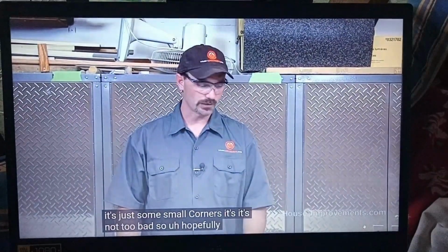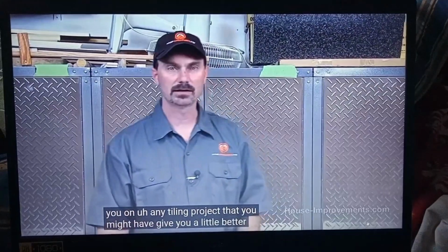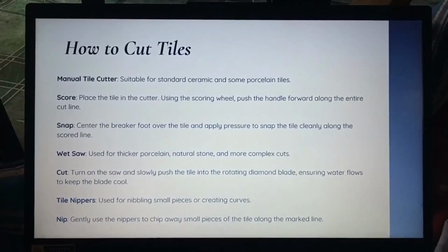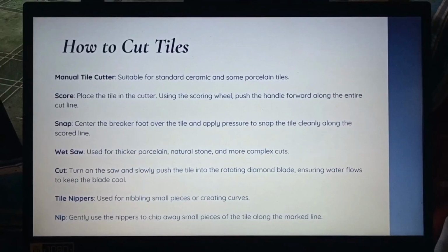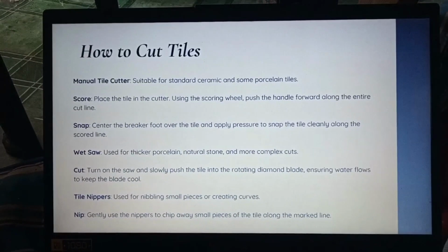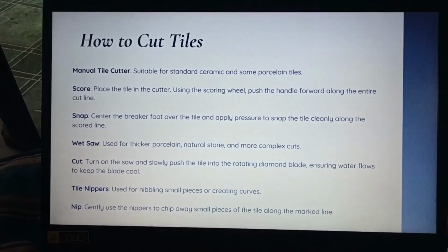So hopefully that helped you on any tiling project that you might have. Give you a little better idea what the different tools do. So those are the three types of how to cut tiles, which are the manual tile cutter, the wet saw, and tile nippers.